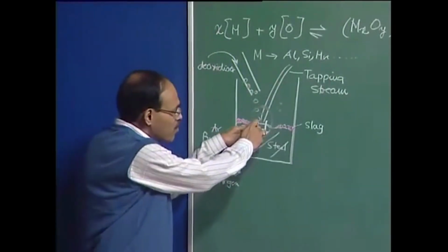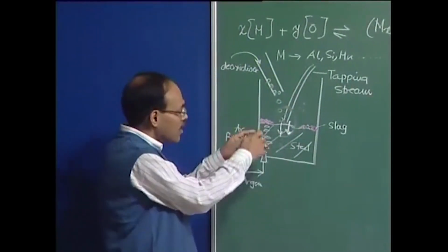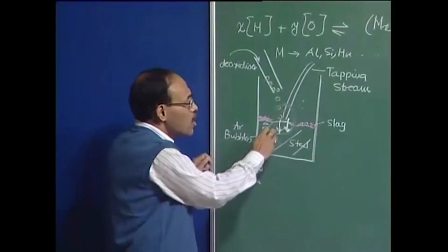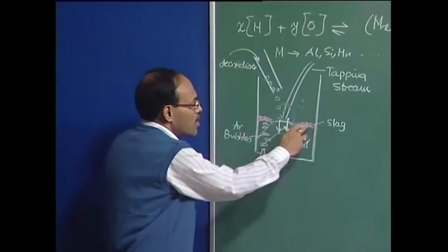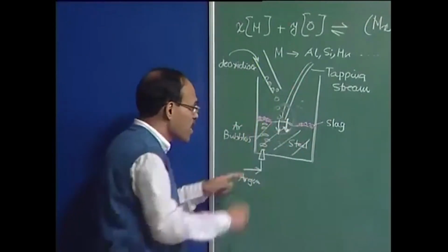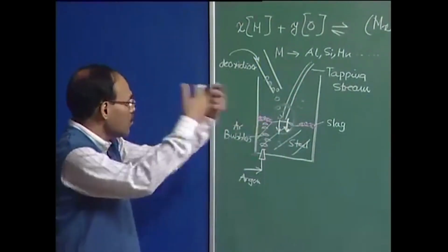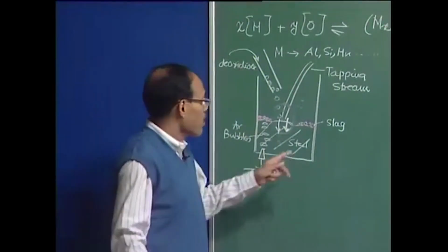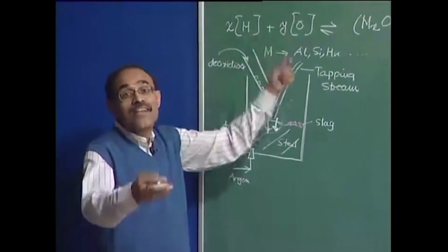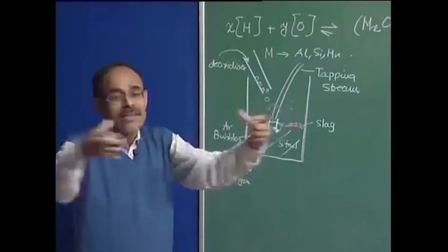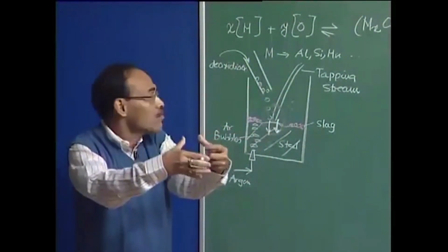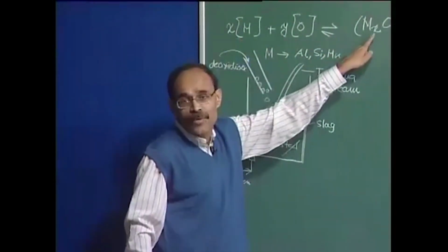As the deoxidizer elements get inside the bath, they melt and dissolve, react with oxygen, and slags form. I have shown with colored chalk here the formation of the slags, and simultaneously the stirring goes on. Because of the mass transfer reactions, we always want the oxygen and metal to come in contact with each other, and only then is the product going to form.